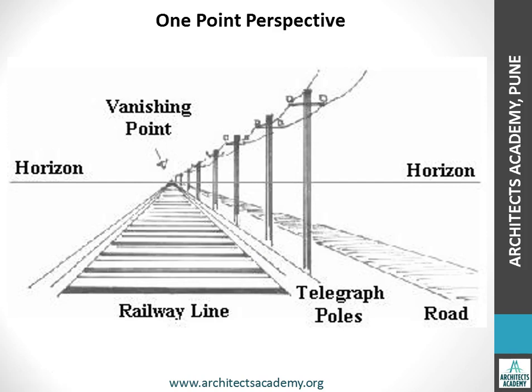But when we look at this railway line from a distance, you don't see the two lines parallel to each other, but you see that they tend to vanish towards a vanishing point, far away into the horizon. This is called the horizon line, and this horizon line also represents the eye level. This particular point to which all the horizontal lines are disappearing is called the vanishing point.